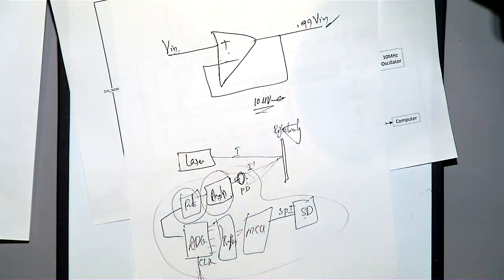I mean, the filter should be before the amplifier. Yeah, you can put an amplifier before as well, but then the signal level is very, very small, so it will amplify the noise. Yeah, that's fine. You can put it before as well, but it might not always be possible. Why? Because in some cases, when you put your filter, the filter can also introduce some noise, like circuit and power supply noise, if the signal is very, very small. So then people amplify a little bit. That's the reason for the concept of a pre-amplifier. They use a pre-amplifier, which amplifies only a little, and then they filter it and then amplify further. Yeah, these things are fine, as long as the blocks are there.